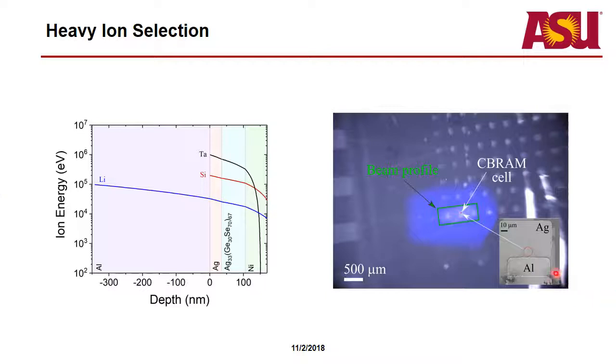And so you see this micrograph here. Again, this is the same mask set as what was used for the silicon ions, where you have the aluminum offset from the actual device area. For this, it's not a raster scanning source. It essentially parks a beam over the device area, and then we watch how the state changes on an oscilloscope. For the tantalum irradiations and one of the silicon irradiations, we were applying a 30 millivolt bias the entire time to read the state on an oscilloscope.